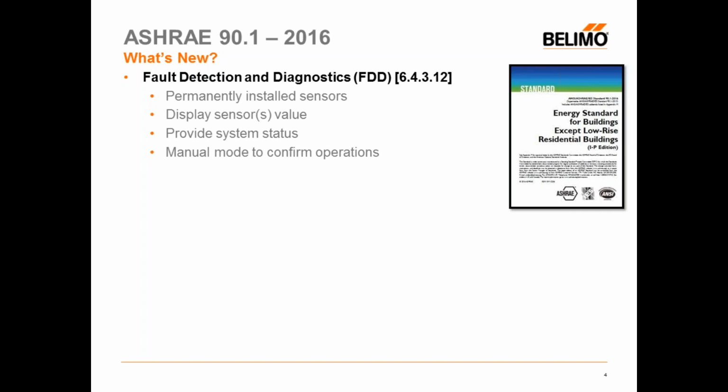The FDD system shall have provisions to manually initiate each operating mode, so the operation of compressors, economizers, fans, and heating system can be independently tested and verified.